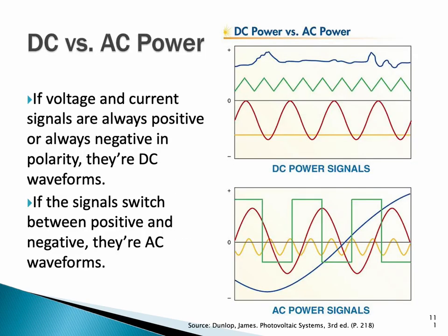So we have this DC signal coming from the solar array made up of modules, and that's going to be straight line DC. Current is going to be variable, but voltage will be there all the time. So then at the inverter itself, to make it usable, we have to create a pure sine wave to integrate into the utility, or a modified sine wave, which is more choppy, which could be used for off-grid operations.